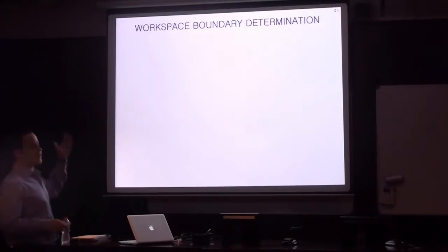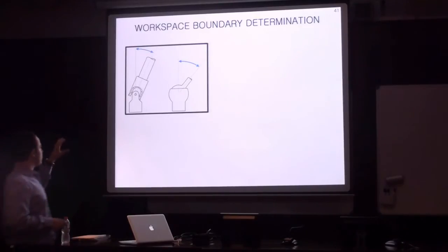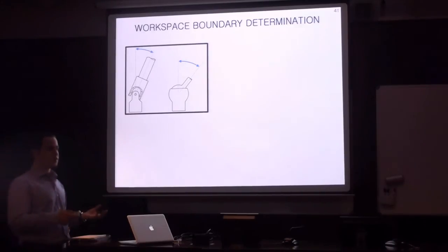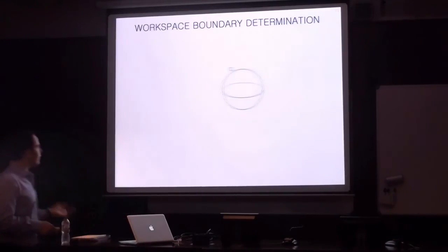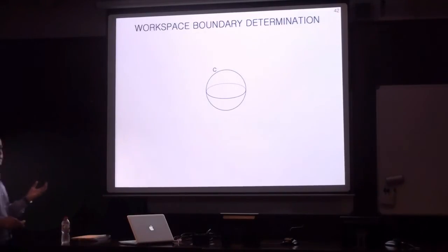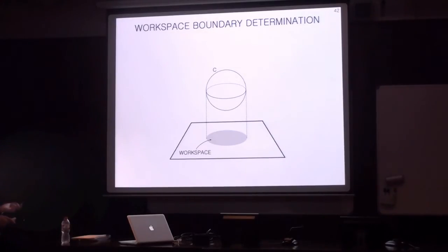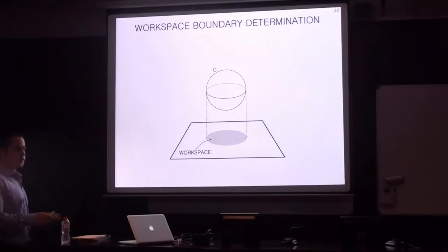All this machinery of singularity set computation can also be used for workspace boundary determination. In this case, however, since the joint limits usually greatly modify the shape of a workspace, we can take them into account in the assembly constraints that define the configuration space. So clearly, the workspace of a manipulator is the projection of the configuration space to the output variables. It is also clear that in the boundary of this workspace, some loss of mobility has to happen with respect to the output variables.